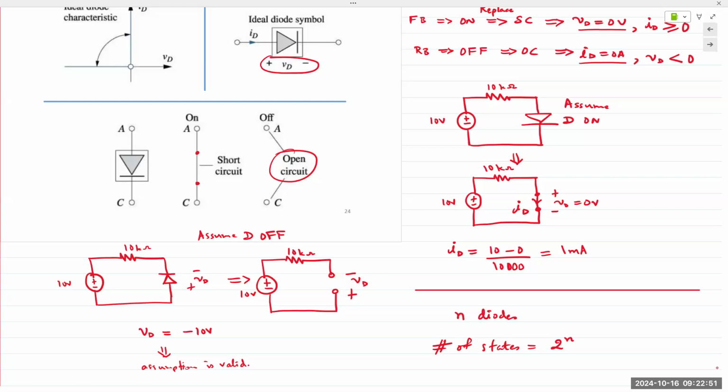If the negative end of a supply, or the cathode, let's say, is decidedly connected to the negative end or is lower than the anode, then the diode most likely is conducting and is in forward bias. If the anode, however, is lower than the cathode, it's most likely reverse bias. So even though there are multiple states that are possible in a circuit, you make those assumptions based on certain logic and rules. Otherwise, you'd be performing multiple analyses all day long.